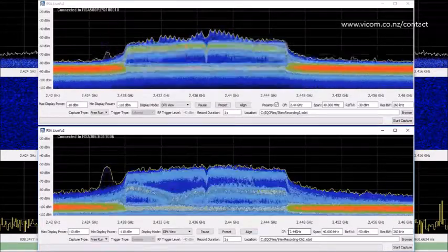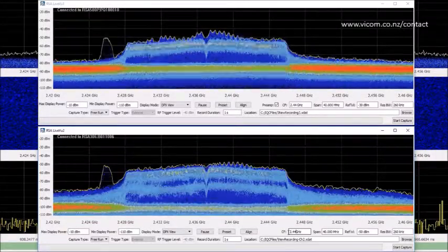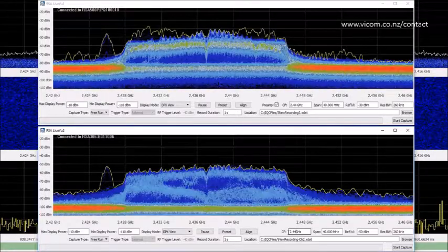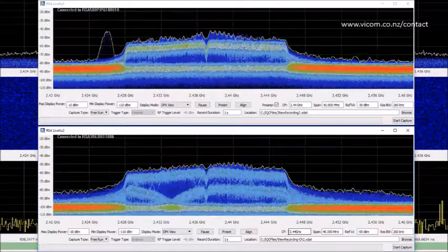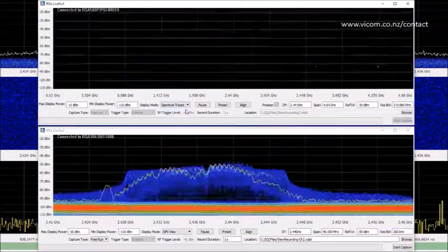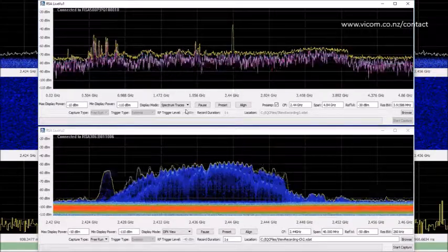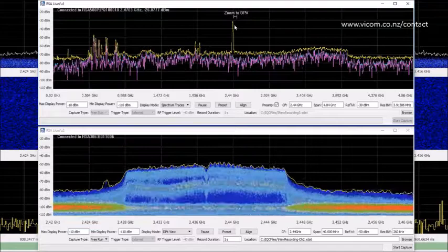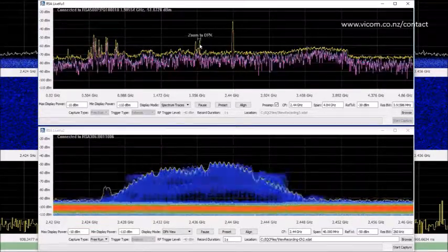You can obviously have different display settings and set the RSA to its own center frequency, span, reference level, and resolution bandwidth. Now let's show a really useful feature for when I'm searching for an unknown signal or monitoring a certain bandwidth. To do this, let's switch the display mode on RSA Live View 1 to the spectrum traces. Now you can see a really wide bandwidth. At this point, we're looking at about 4.8 gigahertz.